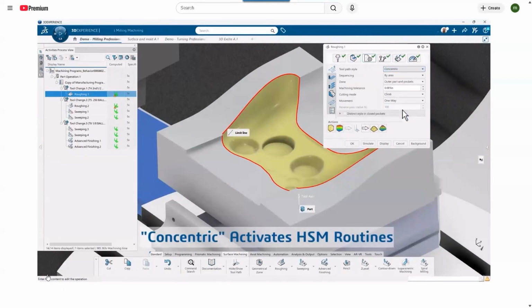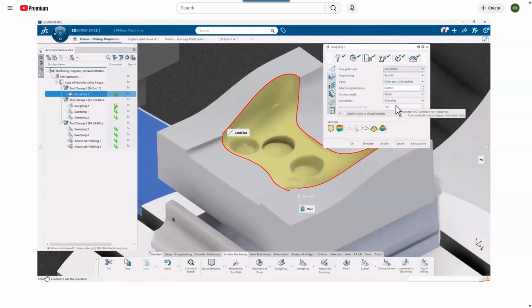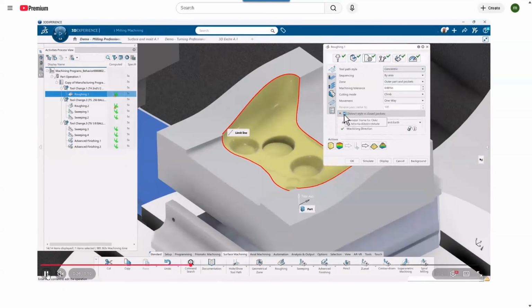because it looks at the geometry and it'll optimize the tool path for air cutting depending upon the geometry shape. So if I were cutting around the outside of this part, the tool path would look a little more adaptive if you're used to seeing other CAM solutions out there, to where we're not going to do a bunch of air moves.